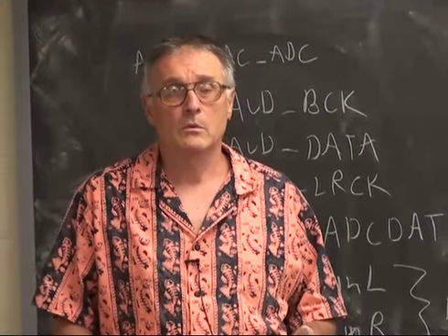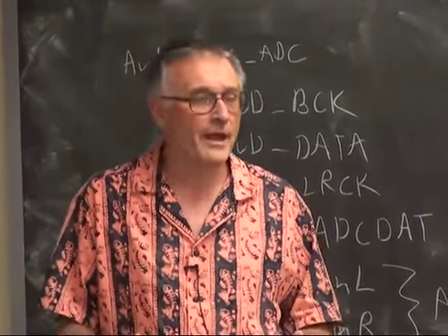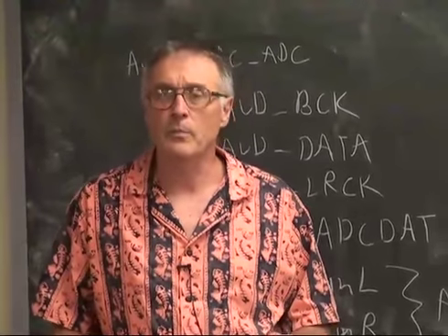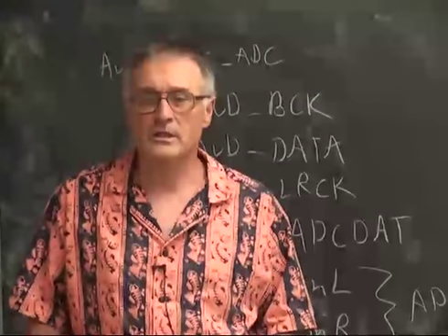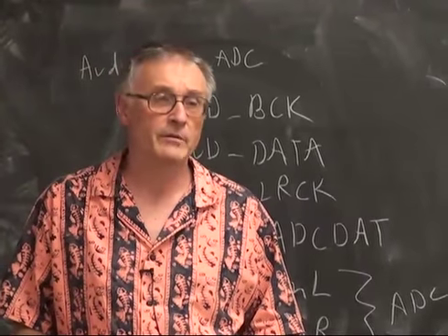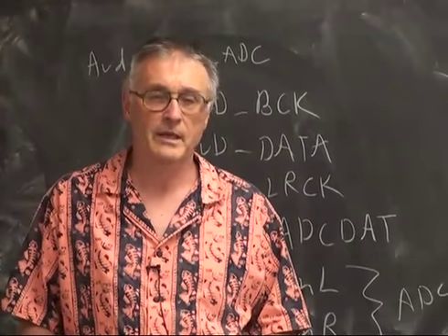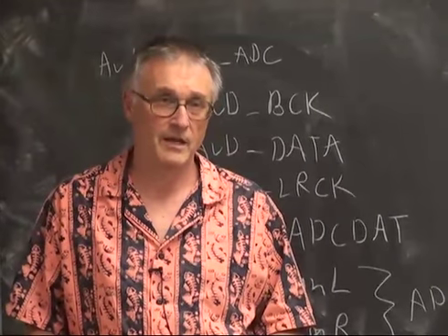So, if you start getting strange behavior of any sort, in fact, in general, whenever you compile something, you should look at the timing analysis and make sure that you haven't violated reality, haven't violated causality. That you don't have a design that cannot be fabricated because of timing errors.